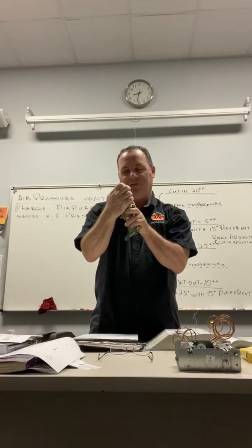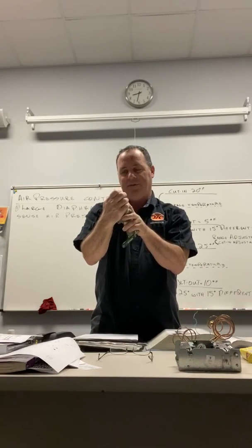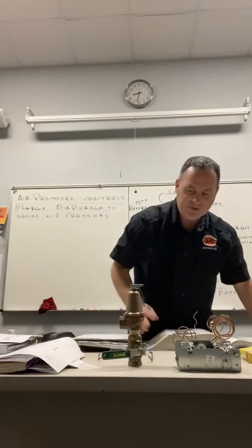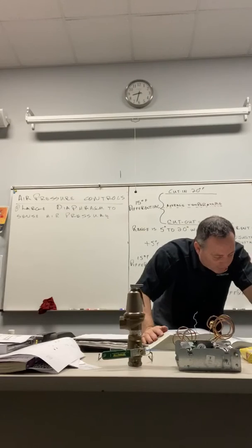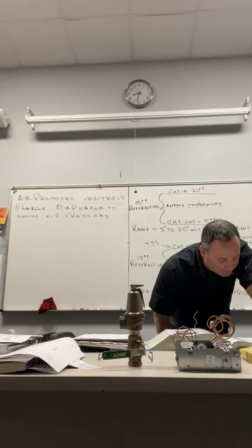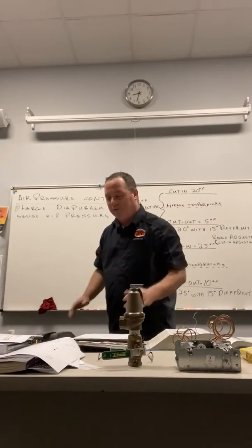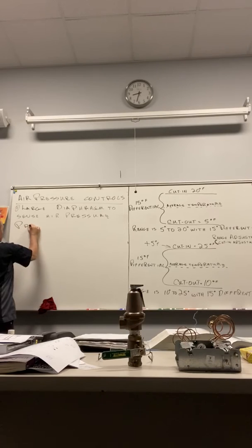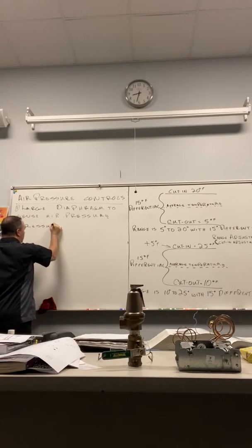And it opens at a certain PSI. This one's set at 75. And when it trips, it releases some stuff. Now look what it says: the pressure setting on a relief valve is factory set and you never fool with it. The pressure relief valve